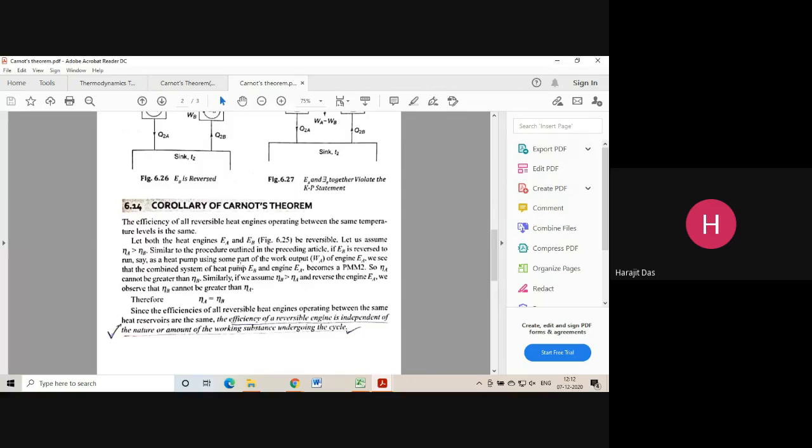Okay, because it generally happens that a refrigerator, which is also a heat pump cycle, has efficiencies or COPs, coefficient of performance, that depend on the fluid. Means it always depends on the refrigerant fluid. But here, reversible refrigerators, reversible pumps, or reversible heat engines will not depend on the quantity, or the amount of matter or working substance. Understood? So it will always be the same.